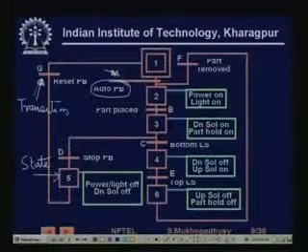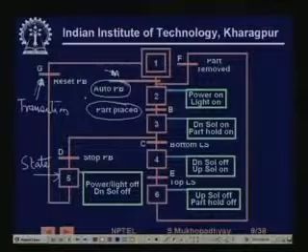In state 2, if transition B takes place, whose condition is part placed, it will come to state 3. So, depending on how the sensors are bringing in signals from the field, the various transitions will be enabled and the system will hop from state to state. That is the behavior of the system.